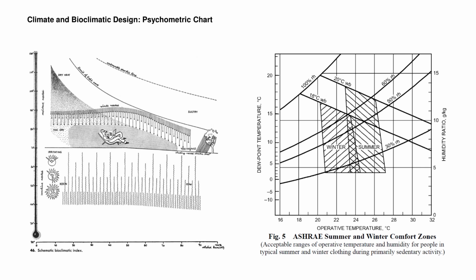For example, when the temperature is 26 degrees Celsius with 30% RH in summer, this will likely feel comfortable, even though the operative temperature is higher than the typical summer set point. This helps us select natural conditioning strategies during the bioclimatic design process before activating mechanical air conditioning.